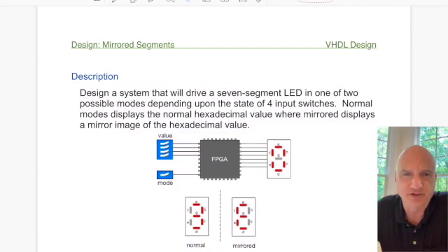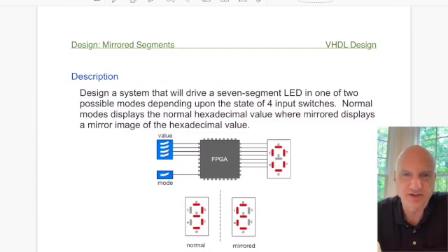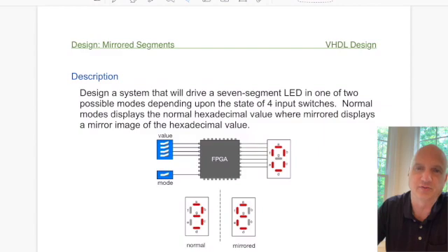Lots of companies have in the past experimented with this thing called a heads-up display. So the heads-up display basically shines the number, like the speed limit, the speed the vehicle is traveling, up on the windshield. So they'll reflect it off the inner part of the windshield, generally in the evenings, when it's dark, but they also can do it in the day if they have a special material that's highly reflective to the light, so that when the person's looking out at the road, they'll see the digits for the speed hovering kind of in the air next to them.